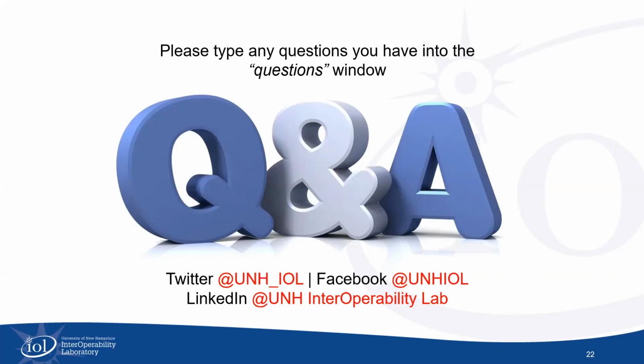And then there was one other that follows up on that. What other areas does QualiPhyer test? Like we mentioned, we are also using the QualiPhyer family in our Ethernet space. Right now we have published packages for the clause 25 PMD and the clause 40 PMA, but there are additional ones we're working on, looking at clause 55 and clause 126 for the 2.5/5/10G BASE-T, as well as some of the BASE-T1 technologies. So we're starting our development of the qualifier for those.